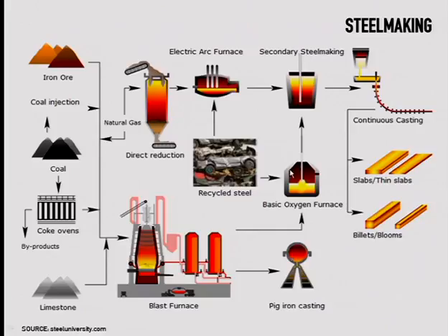I'll show you all of them individually, so that we produce these hot rolled by extrusion slabs. We also get some scrap pieces of steel we want to recycle. In that case, they start from here and they would go to the electric arc furnace. And then the same process, hot rolling, and we get slabs, or very thin slabs.